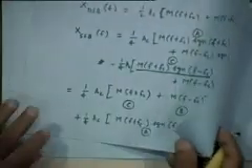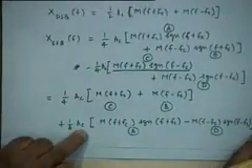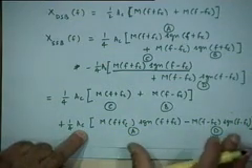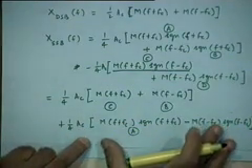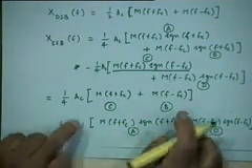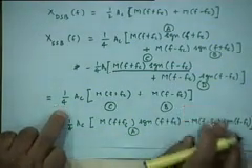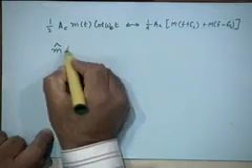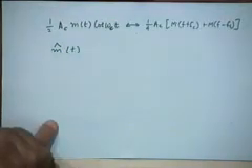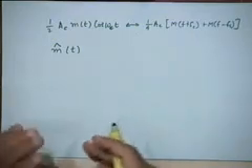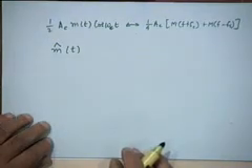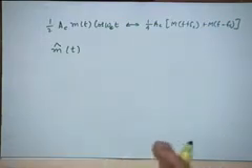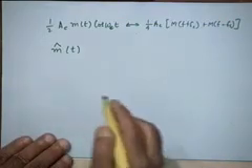However, what the second two terms will amount to is not very clear right now, right? What will be this part of the function is not very clear. So let's try to understand this part. This part is clear in the time domain. Okay? So now let's start with this. This is where the Hilbert transform comes in very handy. Remember, Hilbert transform is defined in terms of the signum function in the frequency domain, and we are having signum functions here. So there is a relevance here of the Hilbert transform.